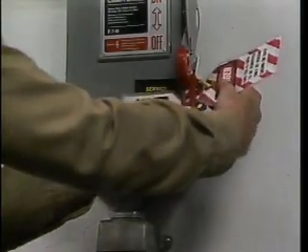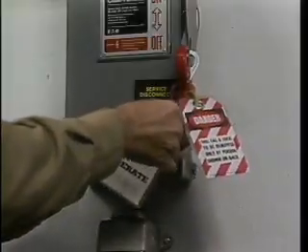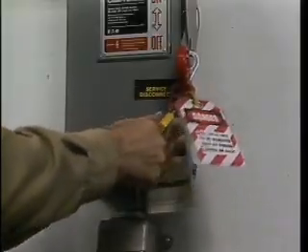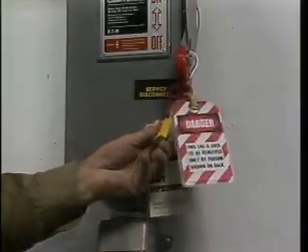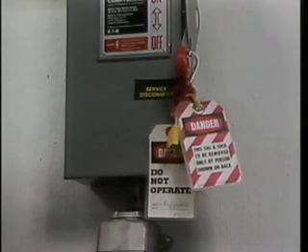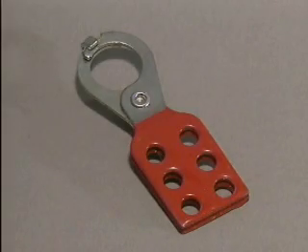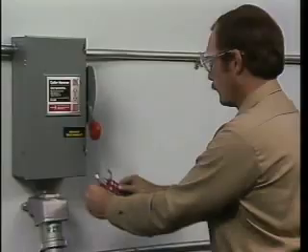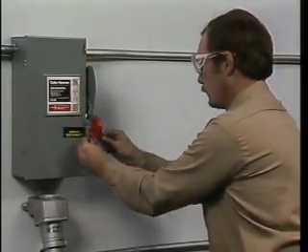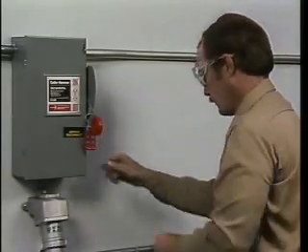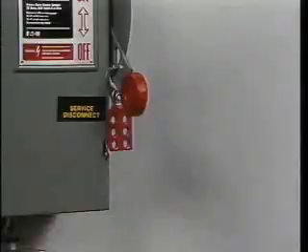What we've seen about lockout and tagout so far basically involves one person. However, major repairs that require several groups of workers are sometimes performed. That's when a group lockout and tagout is needed. In many cases, a device such as this is used to allow each group to affix an individual lock or tag. A group lockout and tagout procedure should provide as much protection as an individual one.